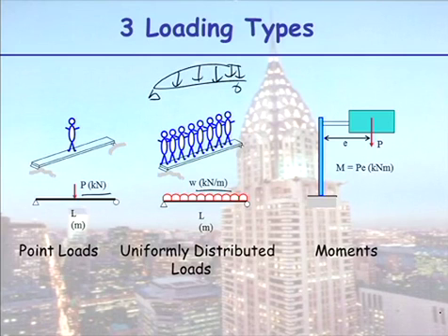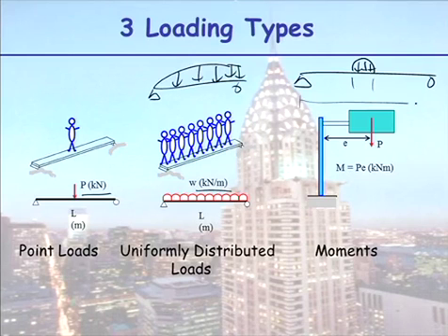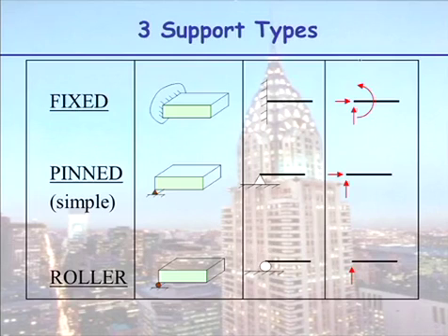So you can look at a structure and say, if you have a long beam and you have this pile of dirt in the middle here, soil, you can go, well, that's not quite a point load. But if it's actually only acting on a small length of the beam, you would then say, okay, well, let's assume a theoretical point load is acting. So we have to model what's there as best we can and as conservatively as we can.